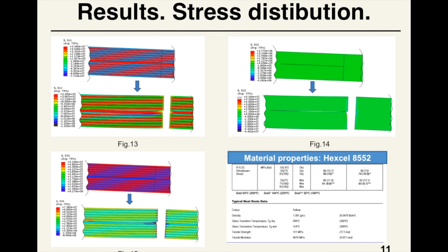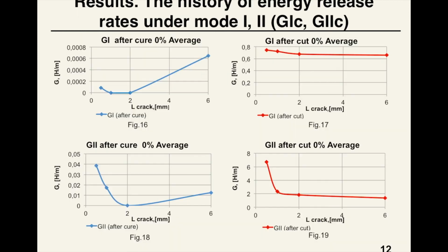It should be noted that the stress in the longitudinal direction is also close to the ultimate value after the mechanical cut and is in a small area at the crack tip. Thus, there is a possibility of formation of microcracks in the sample during manufacturing or at low load, which confirms the conjecture about the reduction of mechanical performance, especially for matrix-dominated properties, by residual stresses.